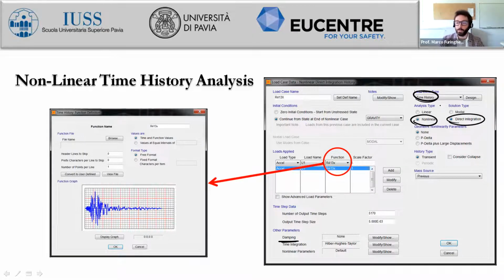There is also response spectrum and so on. An important aspect could be the following. You see here initial conditions. This is important because for rubber bearings, for instance, we start from zero initial conditions. And also for lead rubber bearings, simply because they are just links.